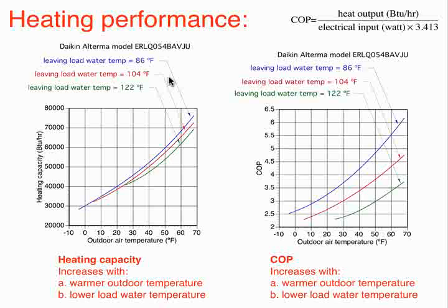So when we think about heat pumps and hydronics, we always want to think about low temperature hydronic distribution systems. Radiant panels, possibly some low temperature thin tube baseboard, some low temperature panel radiators. The criteria I'd like to suggest: on a design day, supply water temperature no higher than 120 degrees Fahrenheit.